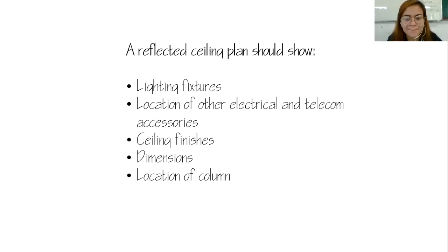Another is the ceiling finishes. If you're indicating on the floor plan that you have certain finishes, then you also need to indicate it on the ceiling.